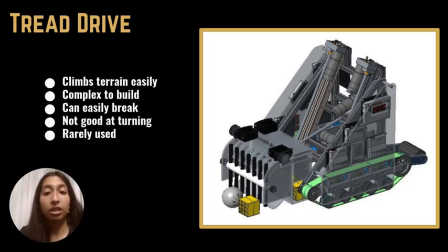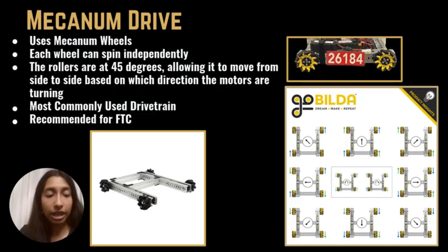Okay. So now we're going to look at our tread drives. Tread drives allow these robots to climb over obstacles more easily. However, they're very complex, fragile, and they're very bad at turning. That's why they're not often seen used in FTC.